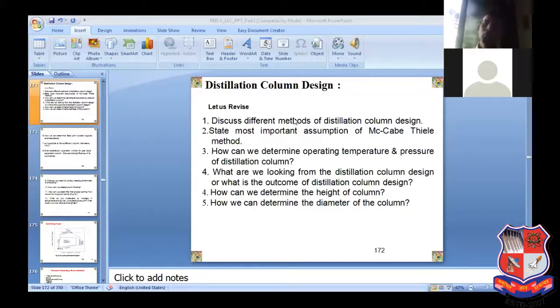So if you go for the water temperature, fine, maybe ranging from 20 to 30 degrees centigrade. Is it possible? Can you achieve this range of 20 to 30 degrees centigrade of inlet outlet water? Even if you design from 25 to 30, is it possible? Because your wet bulb temperature itself in a summer season in Ahmedabad is hardly going to be 28, 29 or 30 maybe even.